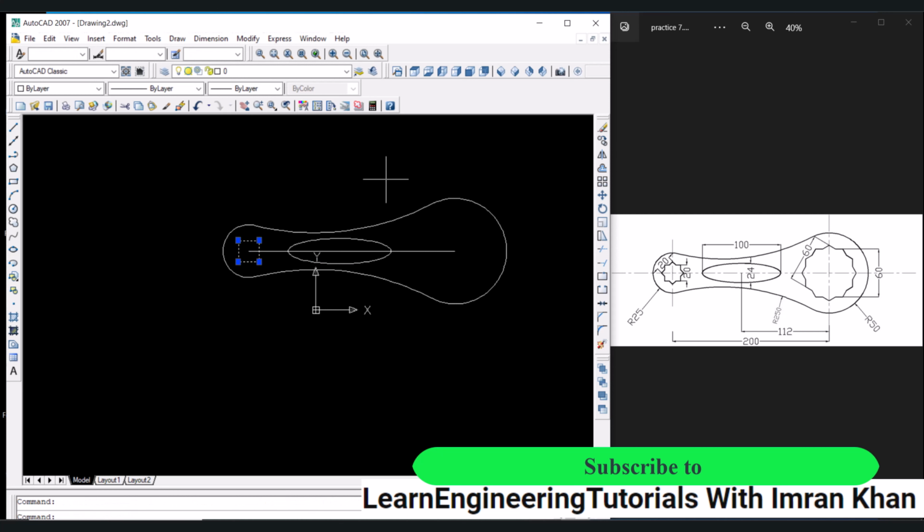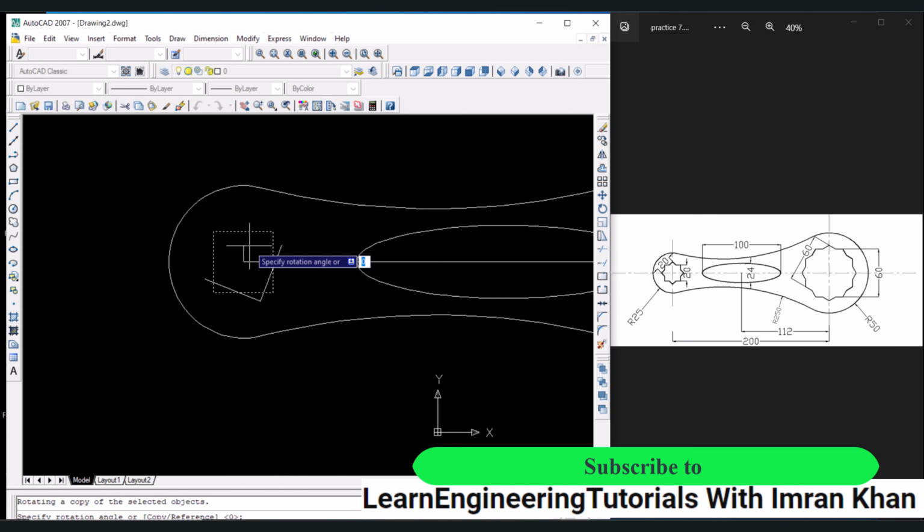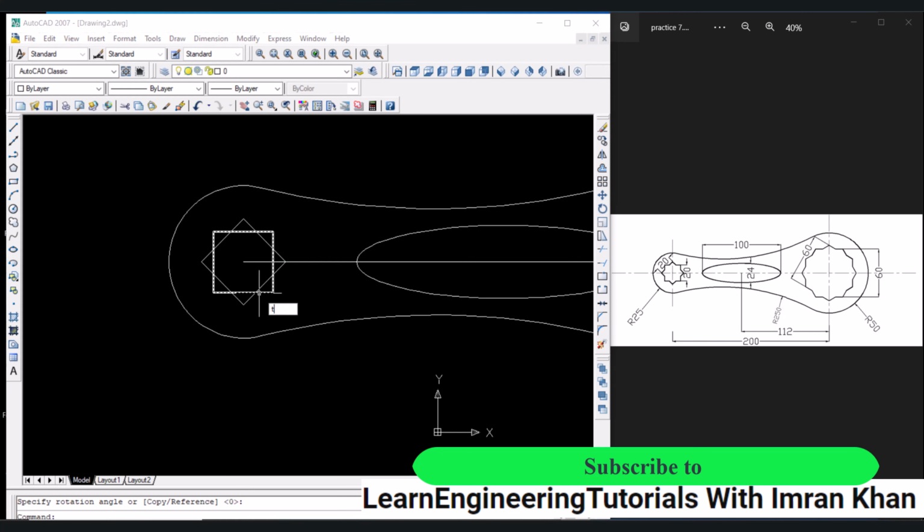Now click on this square, click on rotate icon, select this center as the base point, and now copy rotate it. So here we can see the copy option. For this we have to write C, enter, and we have to just click on this endpoint. We have to now perform trimming, so TR, enter, click on the inner edges,